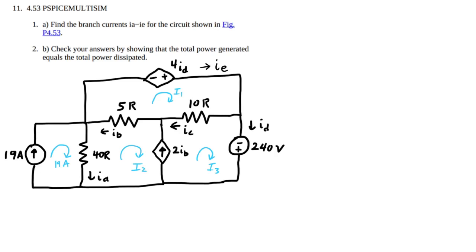Anyway, so one thing we got to notice is there is a branch between these two essential meshes for the circuit analysis, and there's a current source in between them. So just like in nodal analysis, whenever you had, I believe I did earlier, a problem, it was a dependent source, but there was like a V2, V3. So like V sigma equals V2 minus V3.